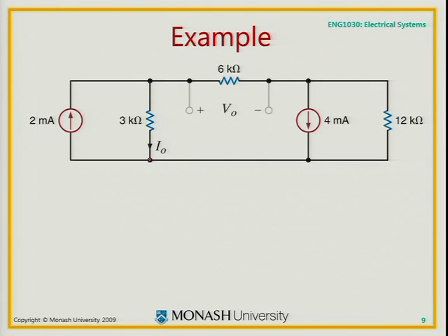So again, I've got to put in my V1 and V2. Now it's Kirchhoff's current law at node 2. This one over here. That current, what's that current? V2 minus V1 on 6K now. Remember when I did that current over there, I had it going in that direction, and you told me it's V1 minus V2 on 6. Well, now it's the negative of it. V2 minus V1 on 6.